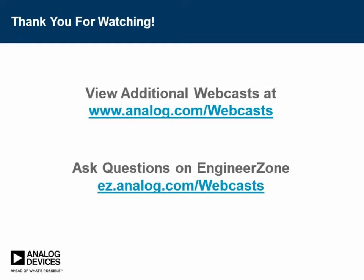This is again a pretty useful thing that you can get on the product web page. You want to look for what's called symbols and footprints, and you click on that, and then you'll go in and enter the type of layout package that you have, and that will then download to your system. You can also get a bulk download of many types of products at once.